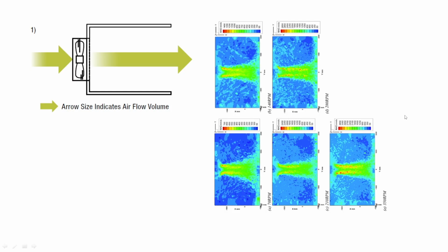This CFM testing: CFM is calculated from the diameter or the radius of your tube, in feet in my case for the calculation. Pi is 3.14, so pi r squared is the surface area, the slice. Then you have the airspeed going through it, in feet per minute. So feet per minute times feet squared is feet cubed per minute, or cubic feet per minute, CFM. Hooray, we're learning some math.